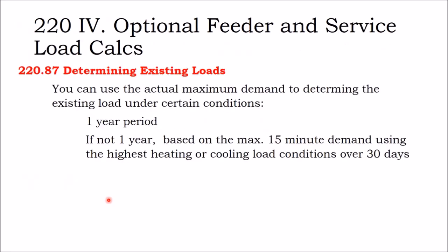Of course, anyone will tell you nothing's better than actual hard data. You can use the actual maximum demand on the existing load under certain conditions: A, if it's a 1 year period, and B, if it's not a 1 year period, what's your maximum 15-minute demand during the highest load over the past 30 days, which of course is not nearly as accurate. So there are allowances on sizing new services based on your existing loads.